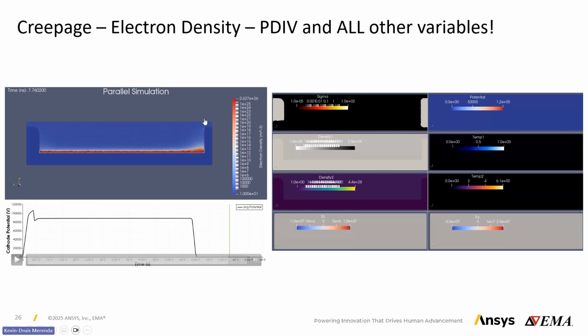And then as you reach the other side, you see the field between the tip of the discharge and the electrode get very, very high as the spark reaches closer and closer to the gap. So you're going to get an acceleration of the discharge once the field gets very high, even probably some electron emission from the electrode itself due to the fields being so high between the tip and the discharge. It happens very quickly, and then boom, we form the conductive channel.